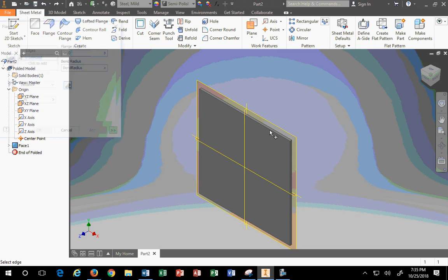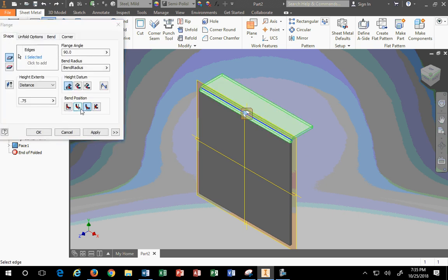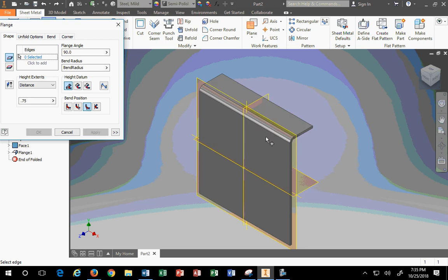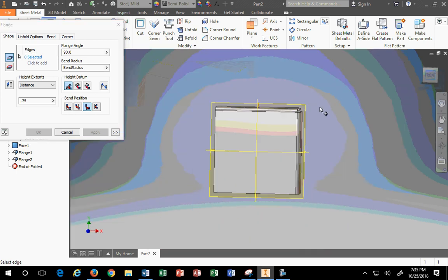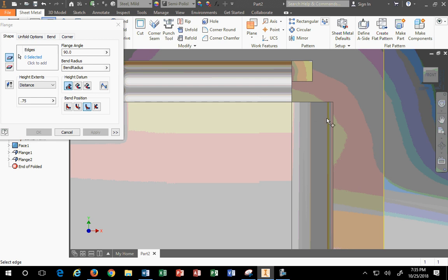When we did the one flange, then we hit apply, and then we did the other flange and hit apply. See how this one was flat and this one had a turn in? This one had an extension to it. If you look at the front, it's still not perfect, not what I want to work on welding, but it's a little better. I would have this thing lapped all the way over to the edge, so I'd have one narrow seam to fill. I don't want a big hole. Okay? To me, that's a big hole.